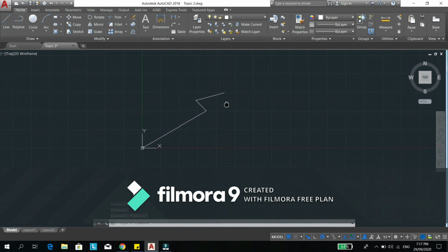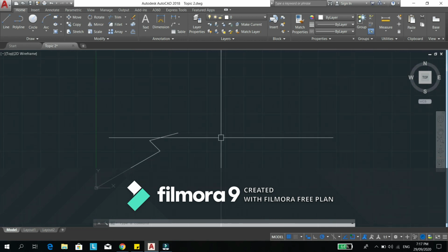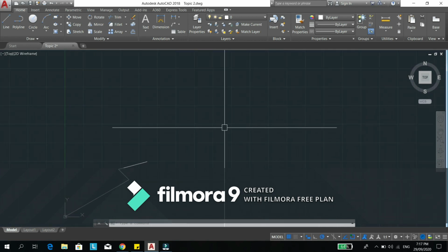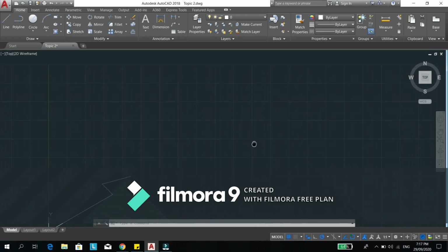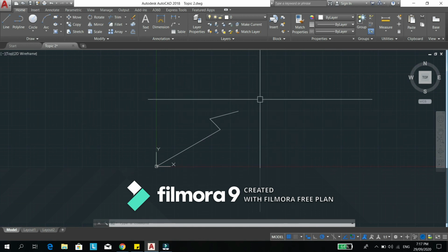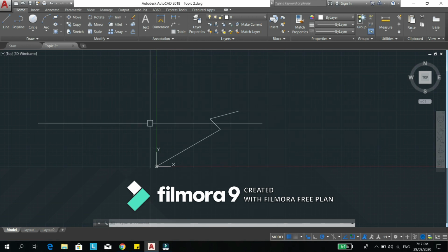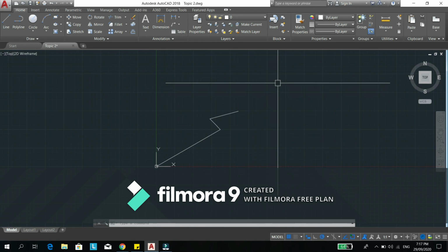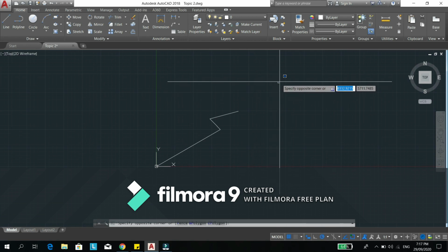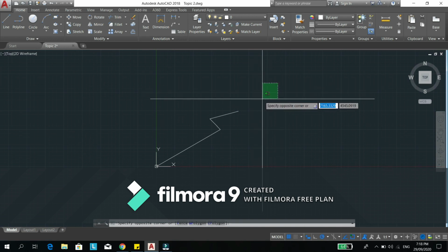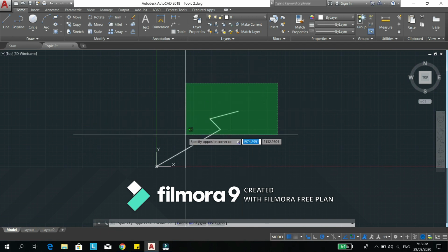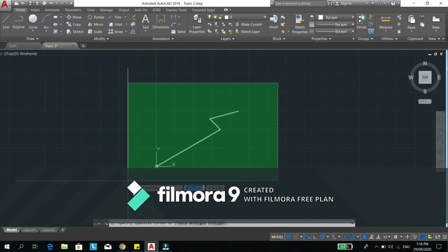So next, before we proceed pala, sorry nakalimutan kong ituro, it's yung selection natin sa CAD. So if you want to select an object, for example, this is the object that we're going to select. If you start from right to left, you can select all the objects. So for example, I have to click first in any part of the drawing area. You just have to click, you don't have to hold click. And then you will see the green square or rectangle.